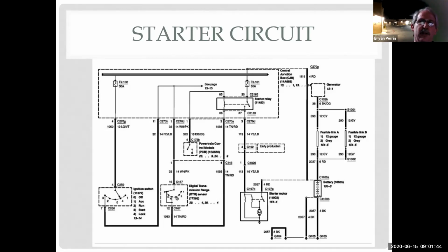So is my car going to start if any one of these 3 circuits has a problem? No. I need all 3 of these to work right before this car is going to crank over. So when someone says, hey, I think I need a starter because I turned the key and nothing happens, is that a guess or do you think they know what's wrong? I guess. It's a guess, isn't it?